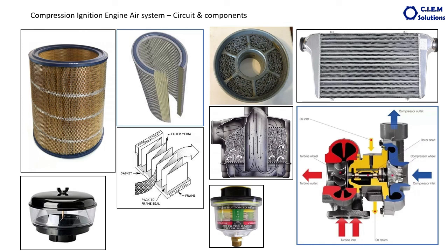There will be some sensors. I told you, particularly in electronic engines, there will be a boost pressure sensor and an atmospheric pressure sensor. All these sensors will give signals to the electronic control module to decide the appropriate amount of diesel to be injected at that particular time.